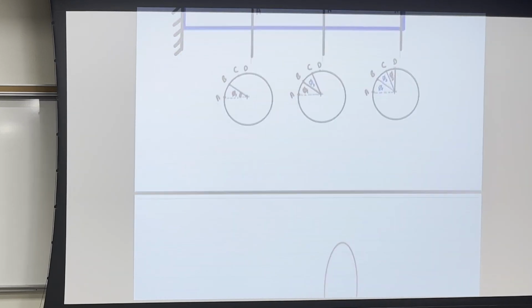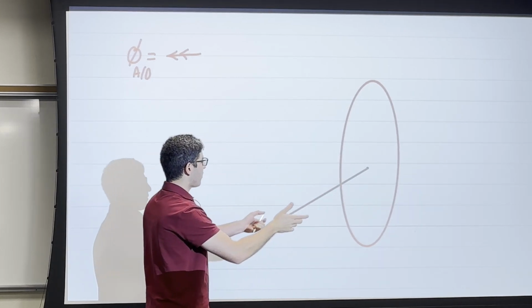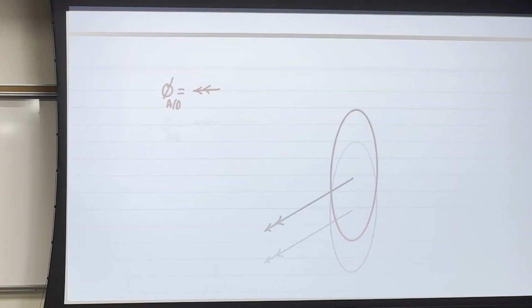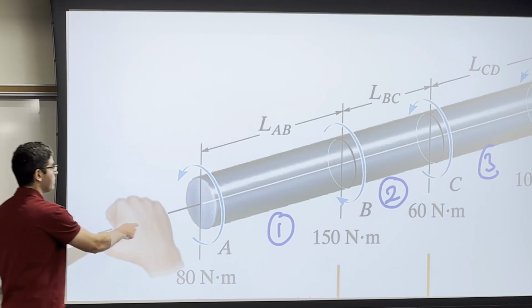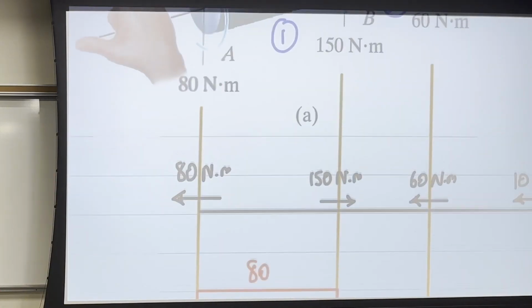So now, for example, this was the shaft at A, right? We're still in this example. So if I got an angle of twist, let me say it away, which is, for example, double arrow away from D. So A relative to D, so away from D. What does that mean? That means that the torque that happened caused the angle of twist to be away from D. So remember, if we want to now reverse what we had before, in the question we had a torque in this arrow form, and then I had my finger follow the arrow and my thumb pointing towards whether inward or outward, and that's how we draw this.